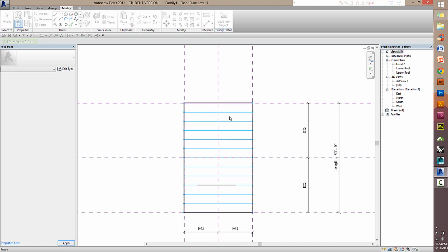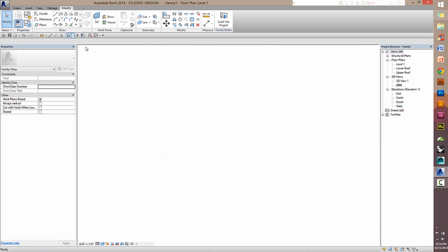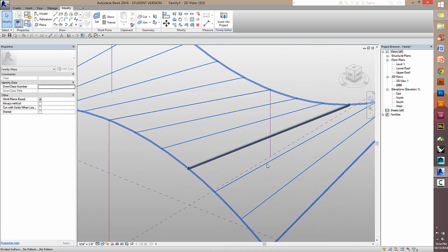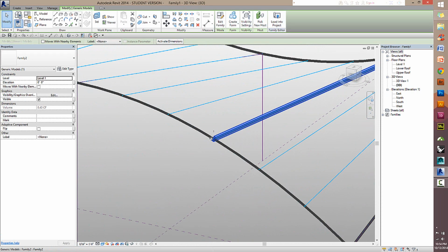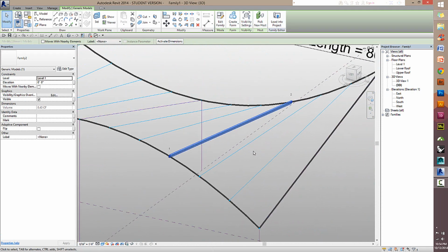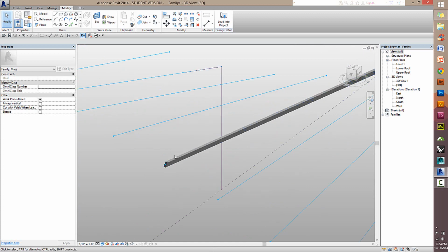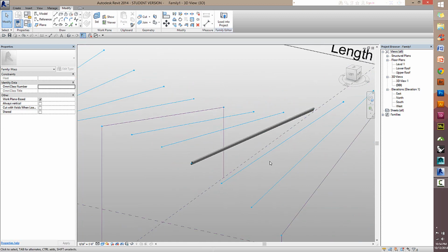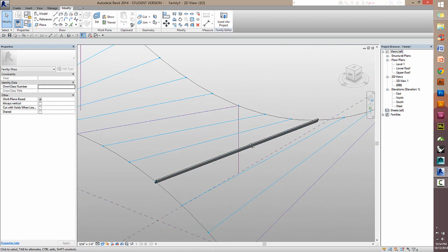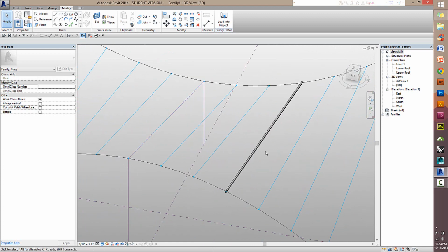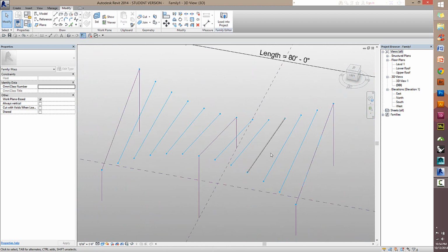We didn't change the parameters, so we can just go with overwrite existing version, and you'll see that it instantly snaps into place. And now it moves to the beginning and the end of this line. One little caveat I'd like to mention quick: if these dark lines along a form are ever bothering you, you can type in the shortcut TL, and all line weights are set to their minimum. TL stands for thin lines. And I usually like working in this mode when a file gets busier because it can be hard to tell what's going on past all the line weights sometimes.